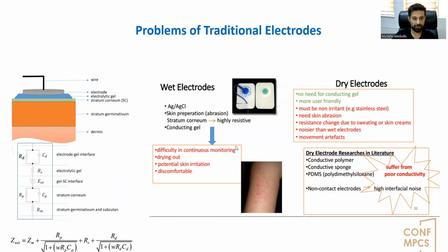In clinical applications, standard biopotential electrodes require the use of electrolytic gel and skin abrasion for a better electrical interface between the electrode and the human skin. Since gel dries out over time, signal deterioration occurs on long duration recordings with these wet electrodes. Dry electrodes are a promising alternative for long duration recording, of course. However, they suffer from high contact impedance and some motion artifacts.